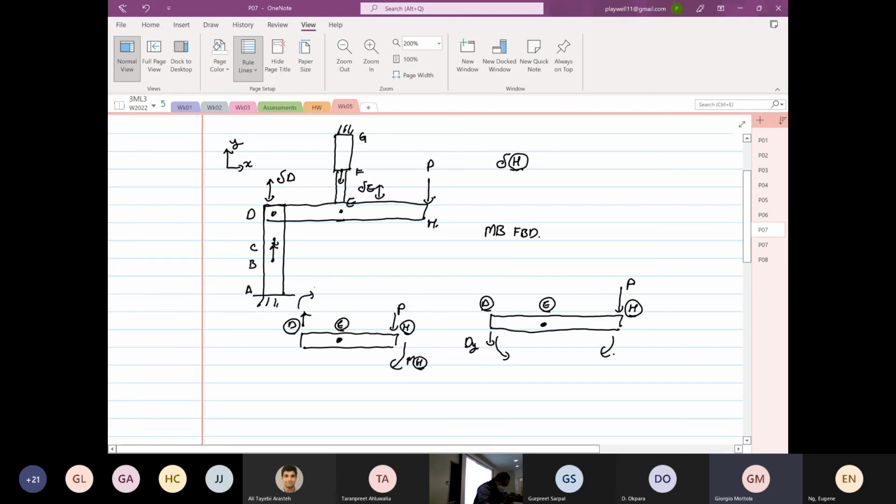The moment at point D will generate a moment in that direction. What will happen to the structure? Rotate. Yes or no? We can't do that because it's known as static analysis. So we know this is coming down. E has to be going upwards, because two loads are coming down. If Ey is coming down, the whole structure will not be static, it will be moving downwards.